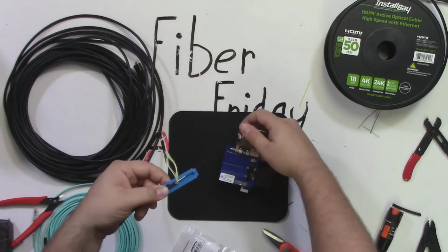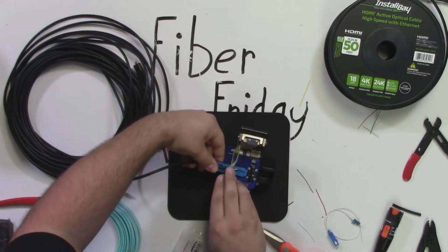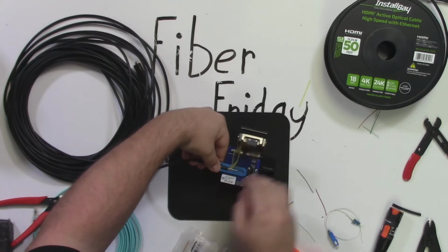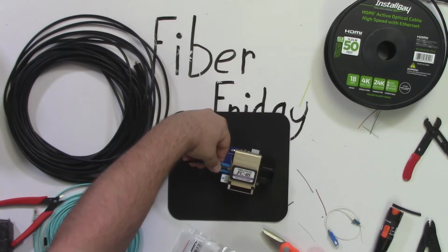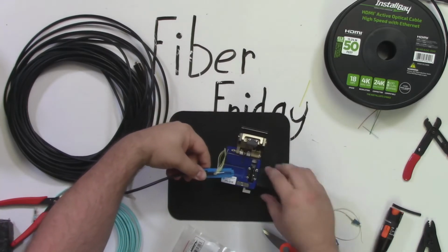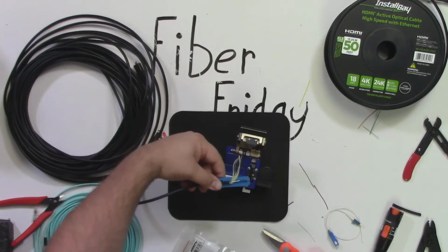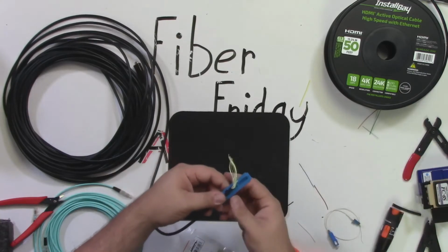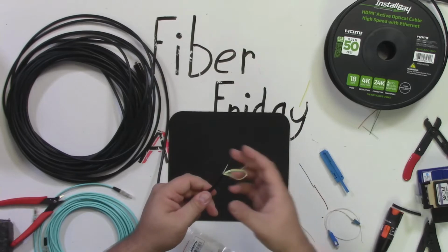So we're going to go in here, get our fiber cleaver. We're going to put it in like so. Now, this is a little bit, there we go, just kind of like that. We'll put it down like that. Do the cleaving portion of it there. Open it up. The excess falls into the waste bin because we do not, and actually it did not fall. There we go. Do not leave the fiber strands on your client's floor. It can be dangerous, and it's something that we don't want to do. That's why we include that waste bin on the cleaver.